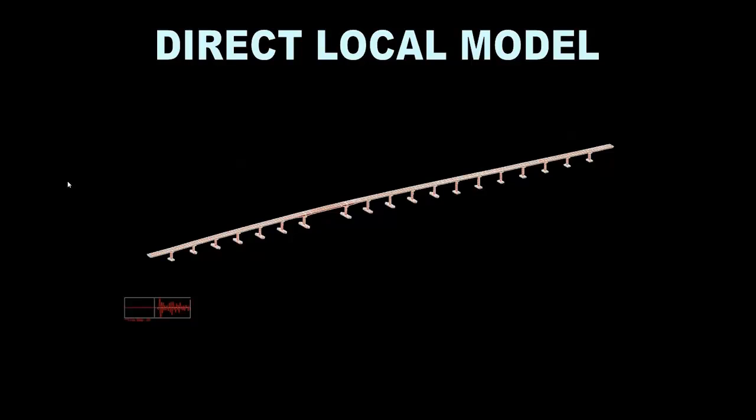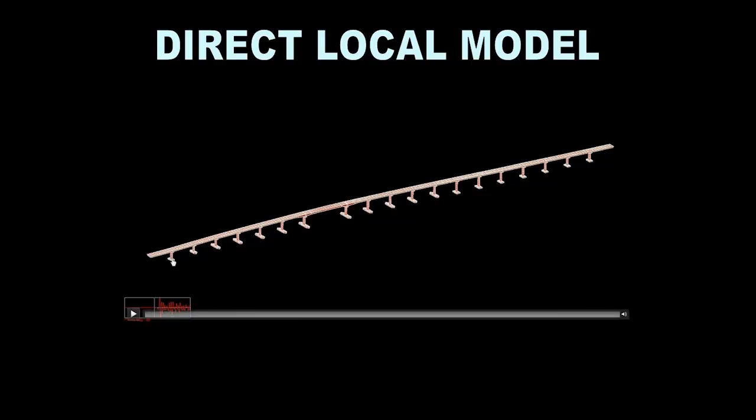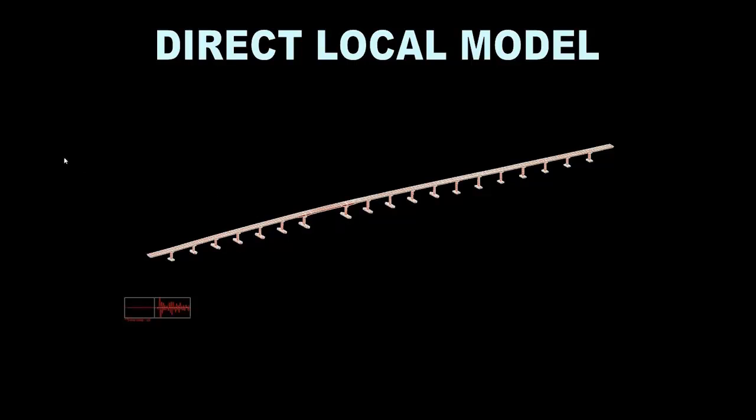Now, I developed this model yesterday. Since I had the model of the superstructure, I decided to also develop a substructure model. And with the substructure model, I put my 6x6 stiffness matrix, damping matrix, and a mass matrix at every location here, and shook the model to see what we're getting.